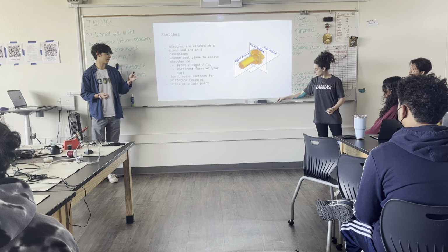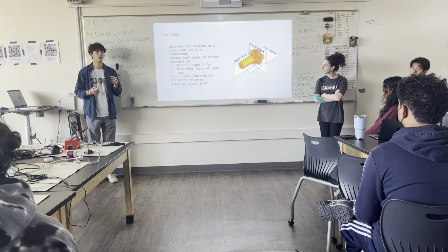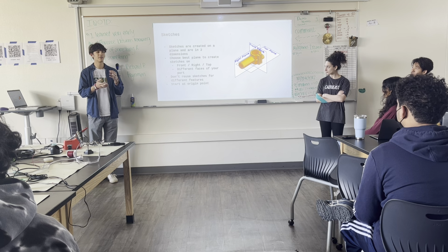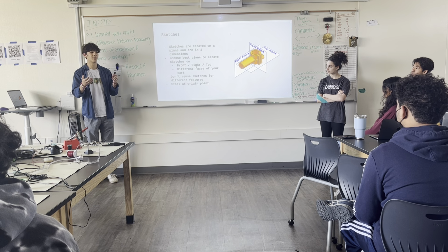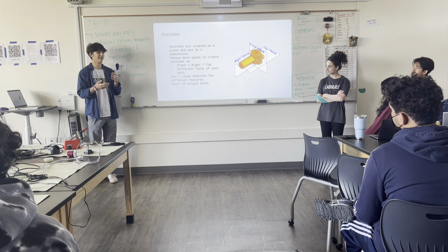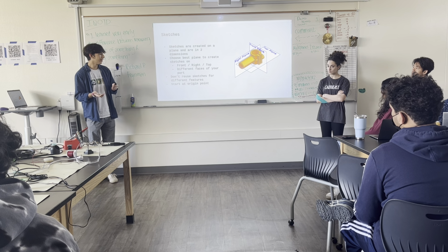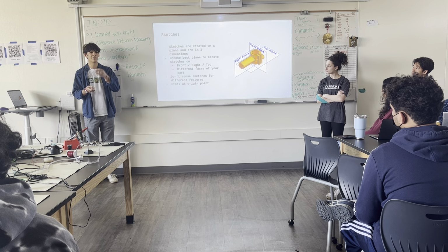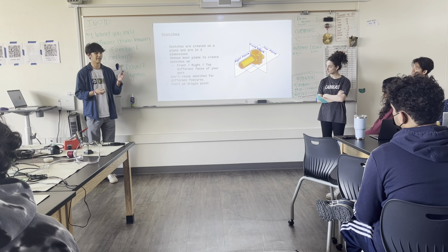And some best practices is to not reuse sketches for more than one type of feature. So if I'm going to cut extrude something, I'll make one sketch for that feature. I'll make another one if I want to do something that's also on that plane, but that's not the same feature. And it's also another good practice to start at the origin point instead of just having your first sketch be floating freeform.